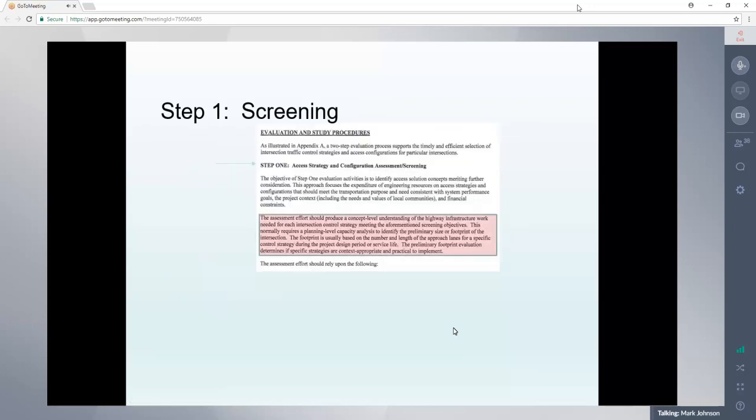We often have an initial screening component to our projects, and one thing we want to be careful of is that we're not screening roundabouts out prematurely or providing over-design that may affect their performance compared to other intersection types. So having an accurate program or analysis, and utilizing multiple tools, including HCM and the geometric model within Rodel, to compare and look at things is important.